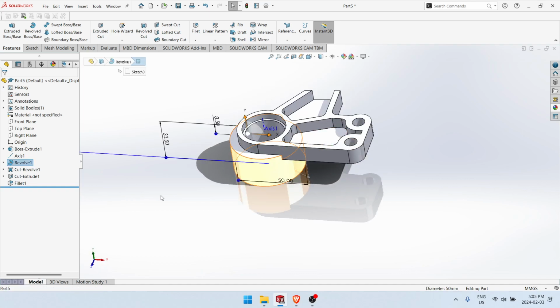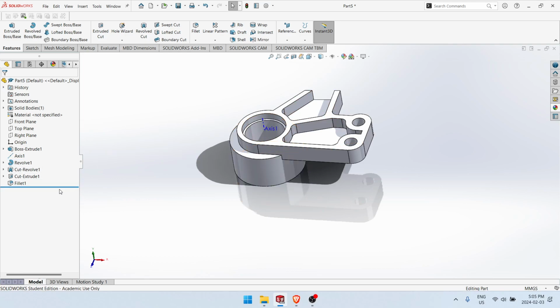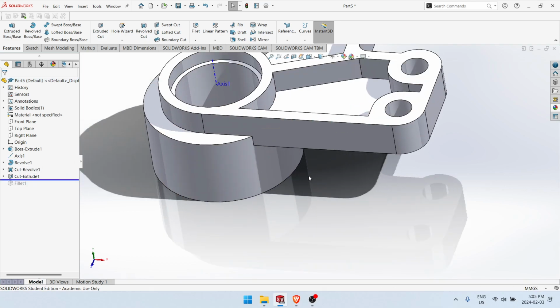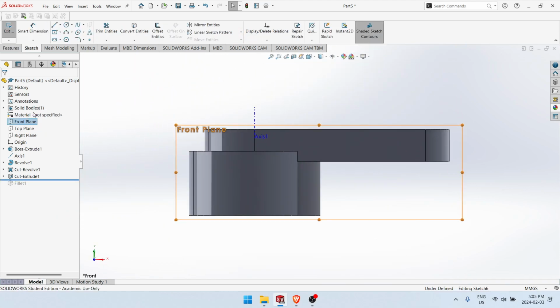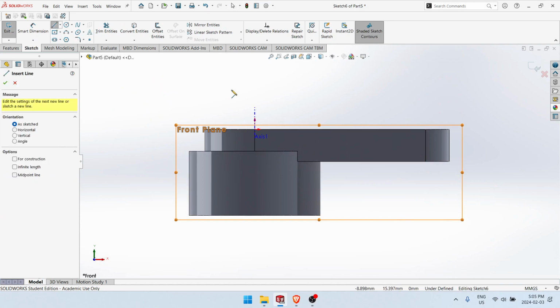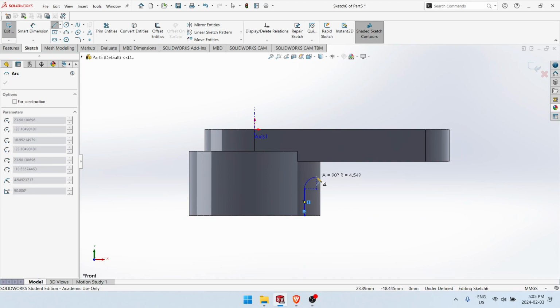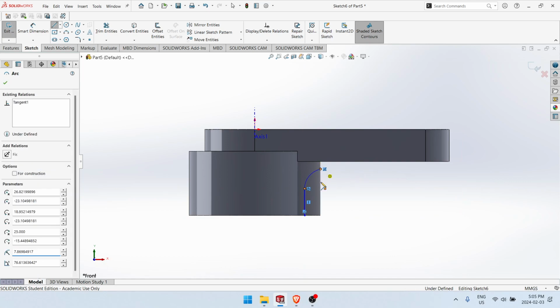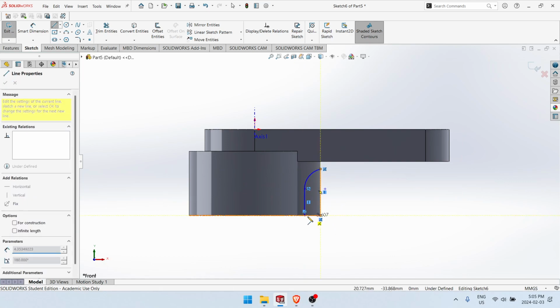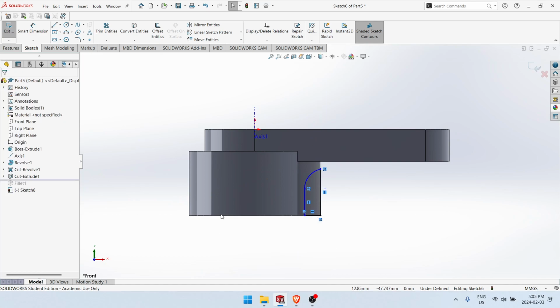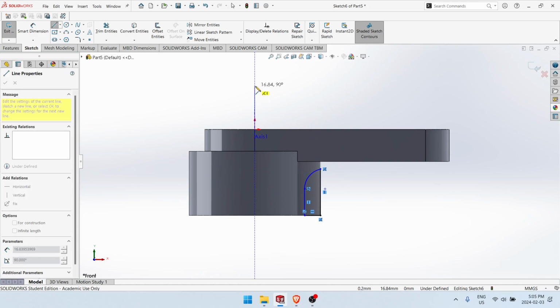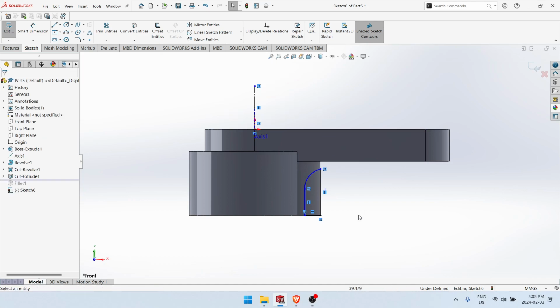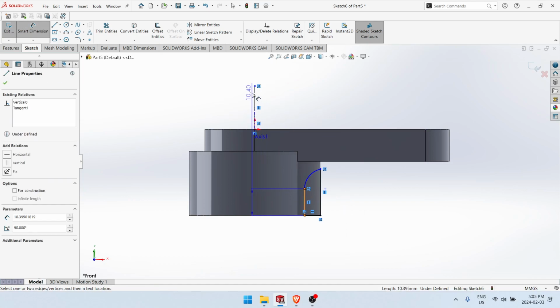Oh no, we just have to do this linear pattern, circular pattern. I'm gonna roll back the fillet. It's not gonna affect anything, but it's just good practice to have your fillet at the end. That actually didn't end up being very useful, did it?